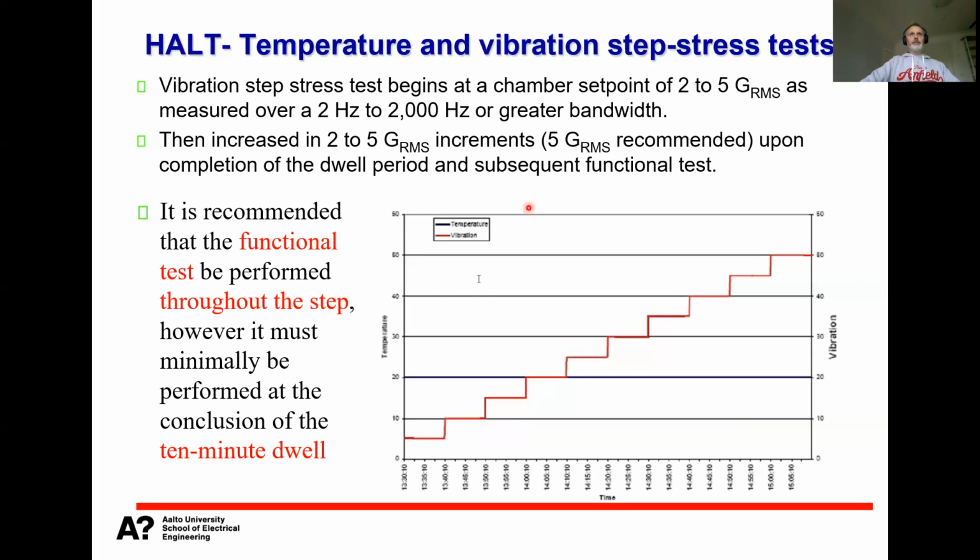How the time of the step is determined? That's a very good question, and basically I have it in the next slide, but I can already say it. For the temperature thermal step test, it's quite easy to define. It's when you are sure that the temperature distribution, the thermal gradients, have evened out. So basically you need to wait until you are sure that the whole product or test unit is at the same temperature as your testing ambient.